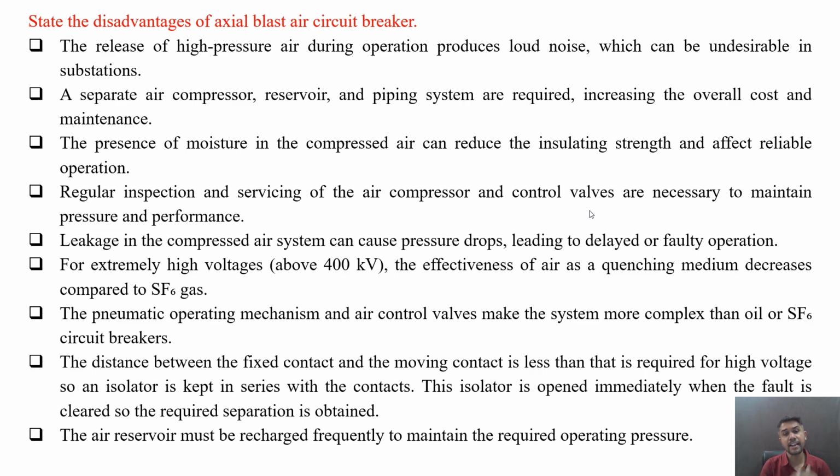Regular inspection and servicing of the air compressor and the control system. All the control valves are necessary to maintain the pressure and the performance. Leakage in the compressed air system can cause pressure drops, leading to delayed or faulty operation.